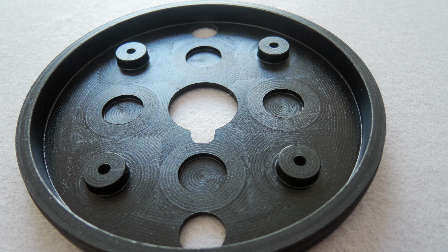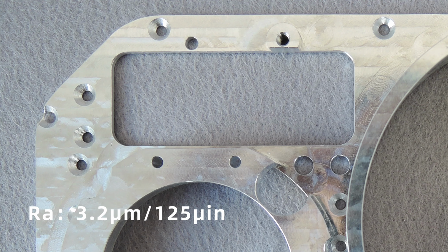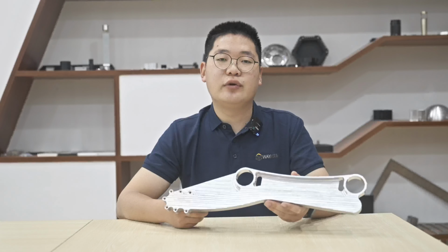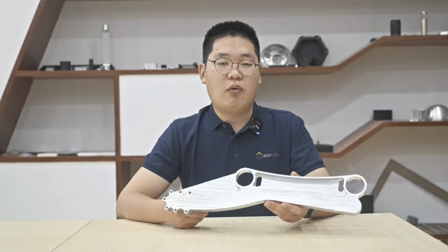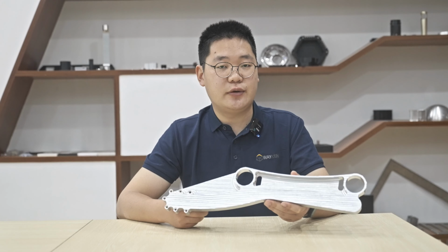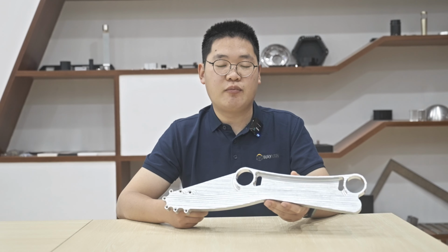The standard surface roughness, or Ra, is 3.2 micrometers or 125 microinches. You can, however, try to reduce the roughness down to 1.6, 0.8, 0.4 micrometers with extra finishing. Just remember that this will add to the cost of your production.